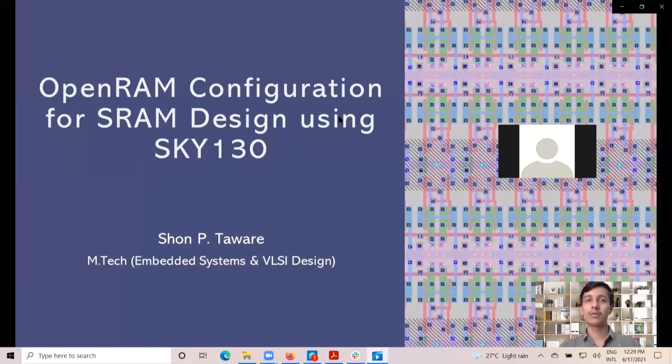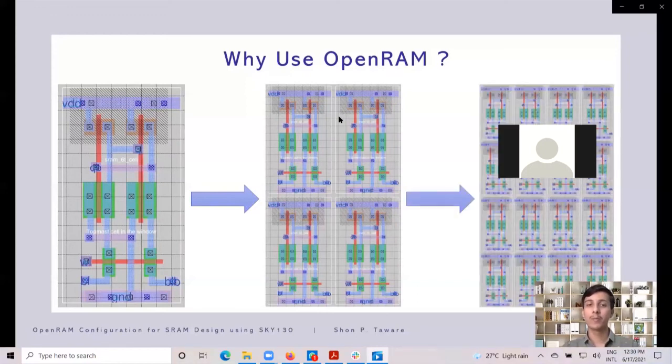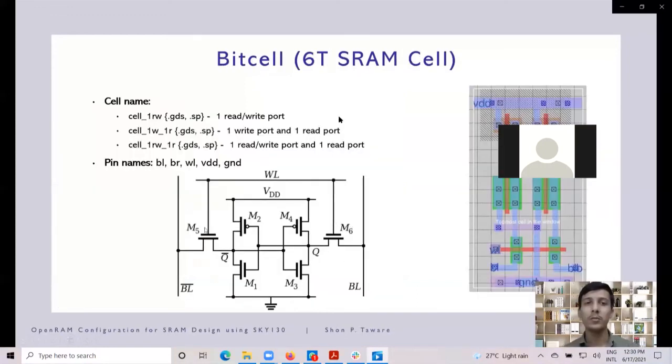So the next figure shows a 2x2 array. Similarly, for a 4x4 memory cell, we need to replicate the 1-bit SRAM cell 16 times. It is designed by cross-coupling two CMOS inverters, which hold the bit, and the two access transistors for enabling the access to the cross-coupled inverters.